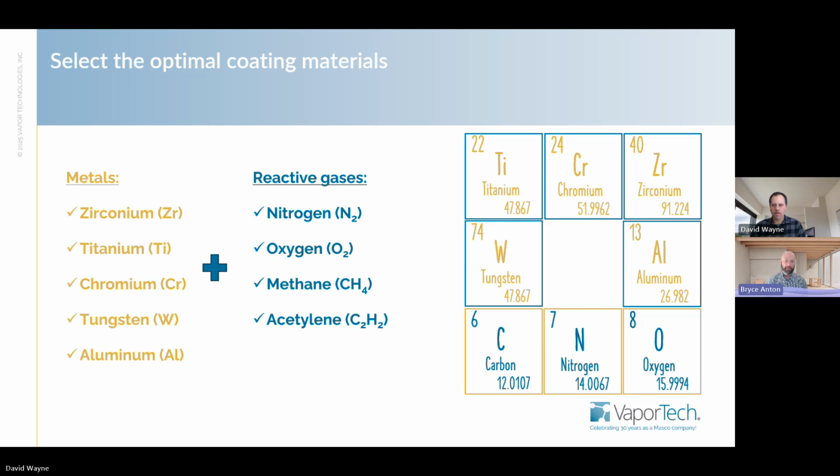Oh, absolutely. That's very, very commonplace. Typically we will get a sample of that coating, and we can reverse engineer using our laboratory techniques. We've got glow discharge optical emission spectroscopy. We've got a scanning electron microscope with EDS. And so we can pretty quickly determine what that coating is comprised of, the different layers, the materials used, and then we can replicate it. We do that all the time. It's a pretty regular occurrence in our business. We have the means to measure the coating hardness, the thickness, any of those attributes that we'll want to then go and match. It's a good question.